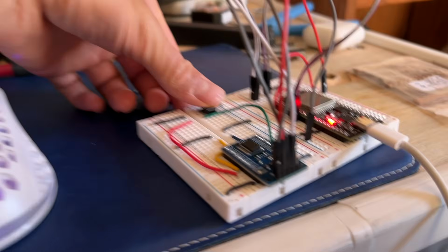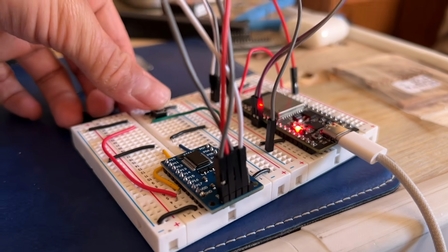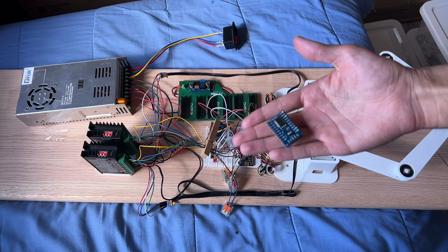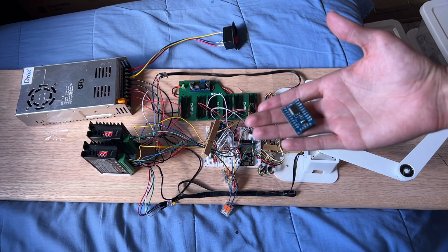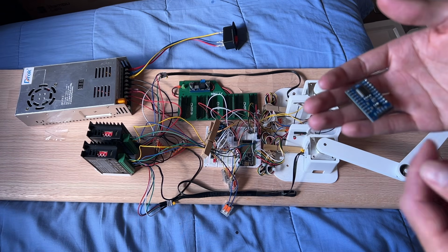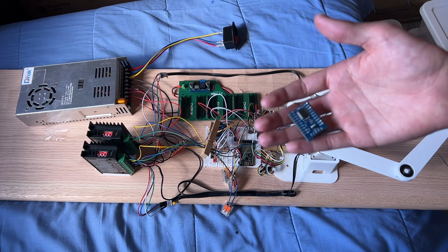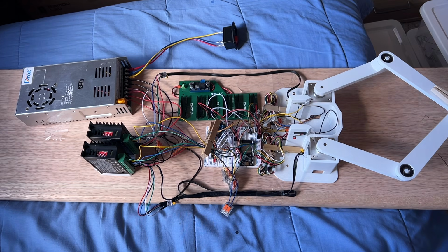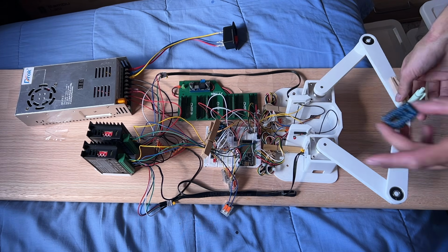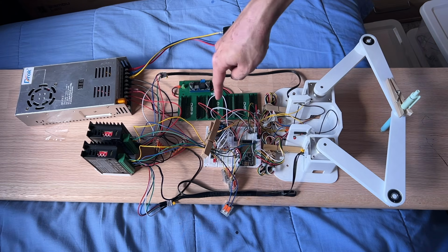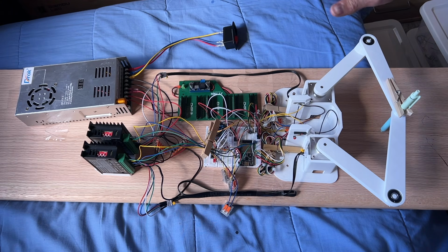I spent all of yesterday trying to figure out how to get this dang thing to work, and it turns out it was super easy. I just had no ground connected to it, and also my I2C pins were plugged in on the wrong side of the ESP32. So we ended up burning today messing around with this. However, we did get it in and all figured out. It's super easy how it works now.